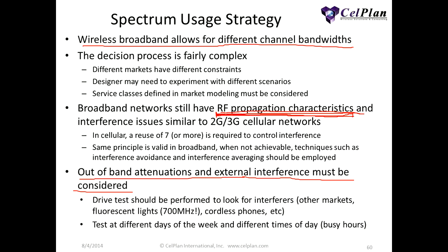One of the things that we have been finding is interference from wireless phones. We found that several of our operators were being interfered with by wireless phones imported from the US that were in the band and generating interference. And this was an interference that would appear and then disappear, appear and disappear.